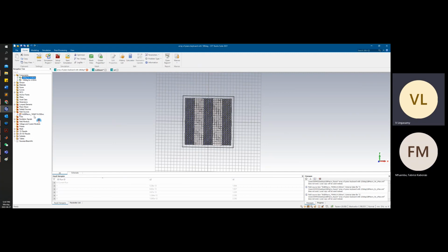You can excite it with anything, but it depends upon the application. See, why are we using a Gaussian beam? In order to mimic some of the antenna characteristics. You cannot ideally see any spherical waves in nature, in any practical antennas. So in order to mimic some of the antenna characteristics, I can use these Gaussian beams, which are customized. For example, if I'm going to use a different feed in practice, I will get that radiation pattern and import it, and that will be used as a far field feed pattern basically.